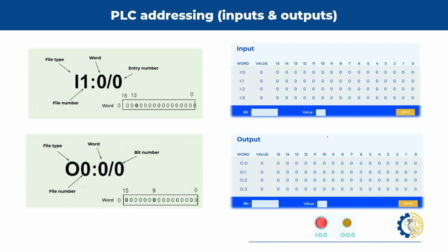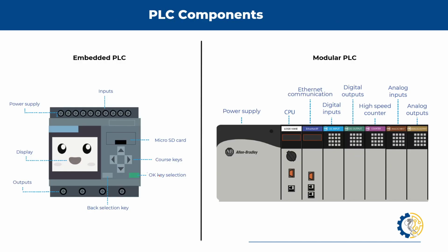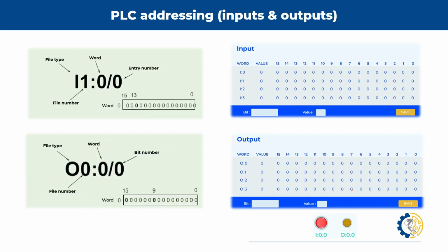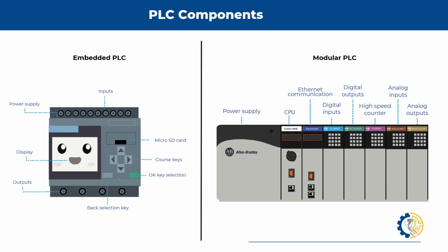Here we have an O, and we also have a file number, which is optional, the module number, and this is 0, 1, 2, 3, module number 3. So then we would have an O, 0, semicolon, 3, dash, and here we have our bit number, which is our point number, where I'm connecting my piston. And where am I connecting this? To my electro valve. Okay, for my 0, point number 3, or wherever I'm connecting it to.